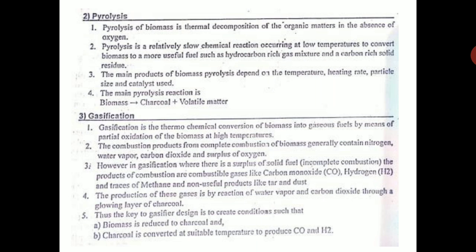And second is pyrolysis. So pyrolysis is thermal decomposition. See here, temperature comes into picture. So it is a thermochemical process. Thermal plus chemical. So thermal decomposition of the organic matter in the absence of oxygen. Pyrolysis is a relatively slow chemical reaction occurring at low temperatures to convert biomass to a more useful fuel such as a hydrocarbon rich gas mixture and a carbon rich solid residue.